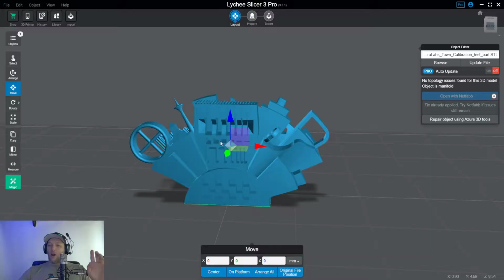So I don't think I can stress enough, temperature is a huge variable. It will make all the difference in the world. Make sure you keep track of your temperature. So tune your print. If the temp goes up, take down a little exposure time. If the temperature goes down, add a little exposure time. And when we say a little, we're talking like 0.1 second, maybe 0.2 seconds. It's not a huge difference, but it's the difference between failure and a successful print. So hopefully I harped on that enough.